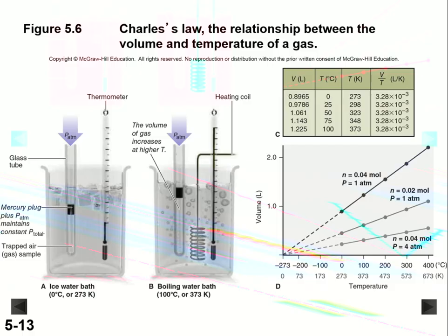So from now on in this course, it is recommended that you use Kelvin scale for all your calculations. You'll find out that you can do some shortcuts once in a while and not have to. If you're doing a difference temperature measurement, you can stay with a Celsius scale. But as a simple rule of thumb, to avoid problems and errors, switch to the Kelvin scale throughout this course.